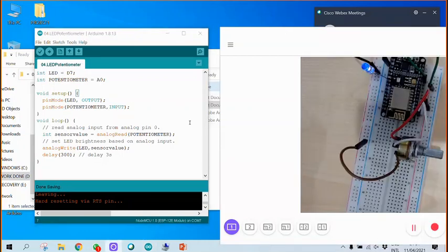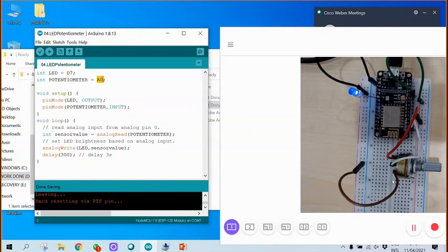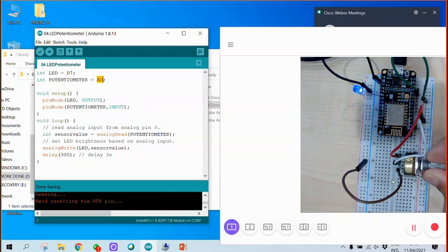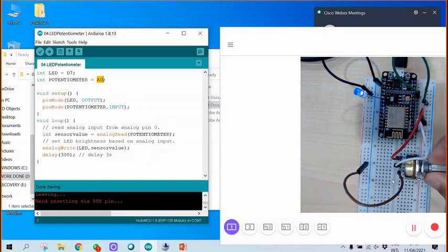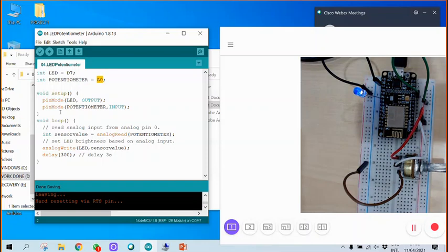However, if you forgot to put the pinMode here, and you call the function, then it will know that this pin is of course the input. Oh, it's already input if you don't put it? Yes, that's why it works. But I think the correct one, you should put pinMode first, and then this is the second thing, and then you can proceed with your coding.